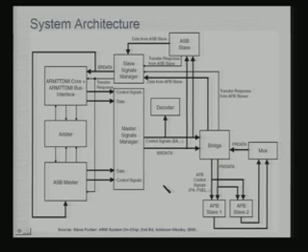So, this is the basic architecture of an SOC using the 2 buses, that is, a hierarchical bus structure, and all data transfers here are in parallel. They are both parallel buses, and your system bus, which can be ASB or AHB, is capable of handling a variety of complex transactions, which gives more flexibility and speed to the bus.